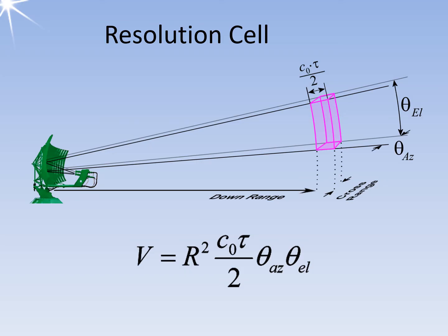The restriction, small angles, in this equation results from the approximation that can be assumed that the sine of a small angle is equal to the angle in radians. When these angles are given in degrees, they should be converted to radians by multiplying by pi divided by 180.